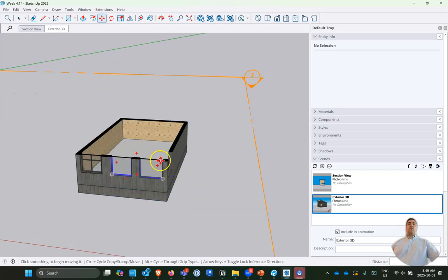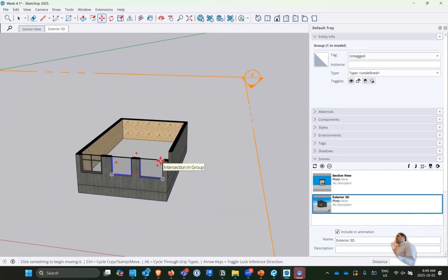So when it comes to floor plans, typically the standard in the industry is you want to cut at 4 feet. So if you can figure out where 4 feet is on your body, going forward, when people talk about floor plans, you want to think, okay, where is my body at 4 feet? That's where we're cutting our floor plan. So we're seeing desks, we're seeing light switches, theoretically we are seeing a little bit of these boards as well. We're seeing the windows. We're not seeing the ceiling, we're not seeing fans, we're not seeing physical lights, so we're just seeing those objects that are below that element.